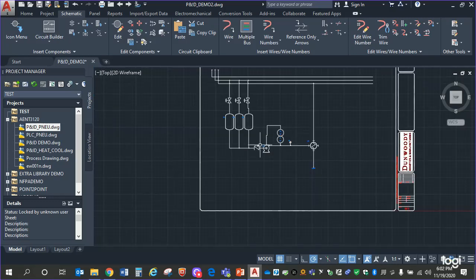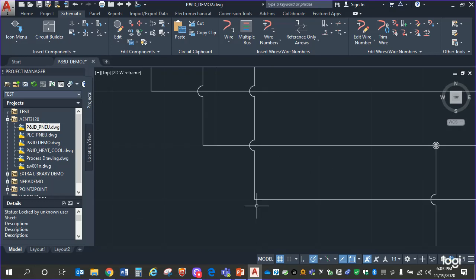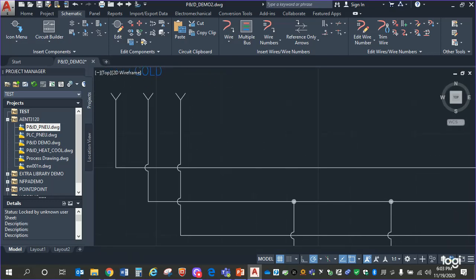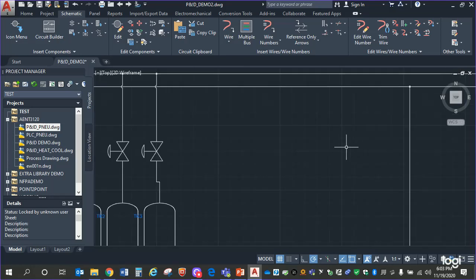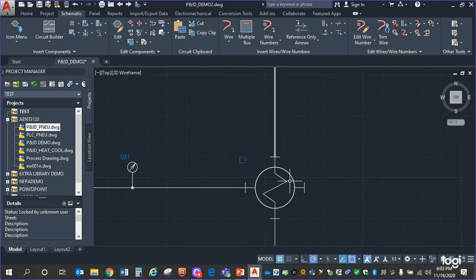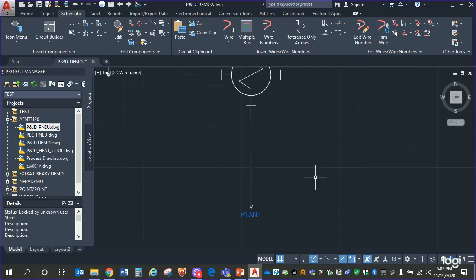Yep. So basically, I'm getting steam from the plant. That steam now is going to flow through that heat exchanger. The cold water is going to pass through the heat exchanger. The steam is going to pass through the heat exchanger. And whatever condensate I get coming out of here is just going to go back to my plant. I'm not as worried about that, but you're right. There's piping, a trap, scuppers, all kinds of things that I have to worry about where that steam is going to end up. All right.